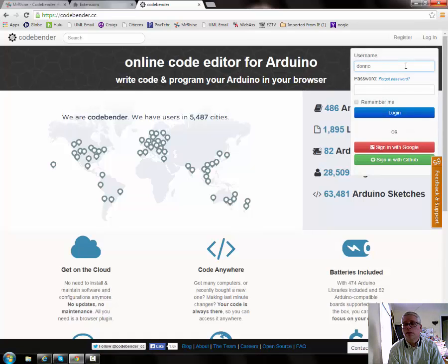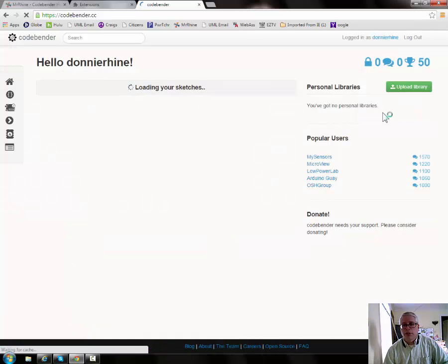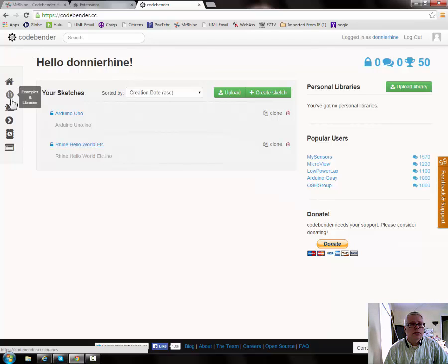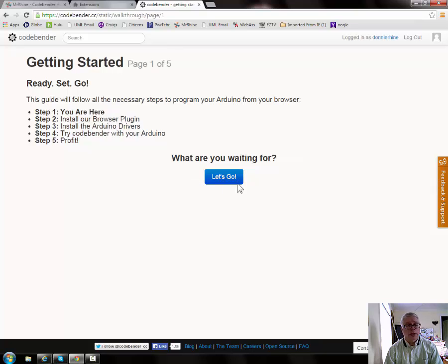So I'm going to log in to the new account I created in class today. All right, so here I am, and let me see if we can find examples, libraries, supported boards. Getting started. Let's go to the getting started. So I clicked on the getting started, and this is what we did in class. It will step me through the process of installing the browser plugin and installing the Arduino drivers, and that's the key thing I need so that our hardware will recognize the Arduino when we plug it in. Step 4 I won't be able to do. Step 4 is to try out Codebender, so you'll have to trust me that that works. So let's go and try this.